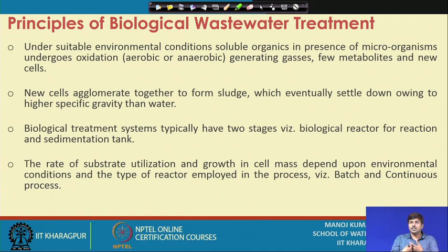We discussed earlier the batch and continuous systems. In batch systems, the inflow comes in batches and remains in the reactor for some time, whereas in continuous systems the inflow and outflow keep happening simultaneously, and based on the design of the reactor we can set up a retention time, the average time the fluid particles spend in that reactor. So, depending on all these conditions, the rate of biological reactions, cell synthesis, metabolism or substrate utilization will eventually depend on the kind of procedure.